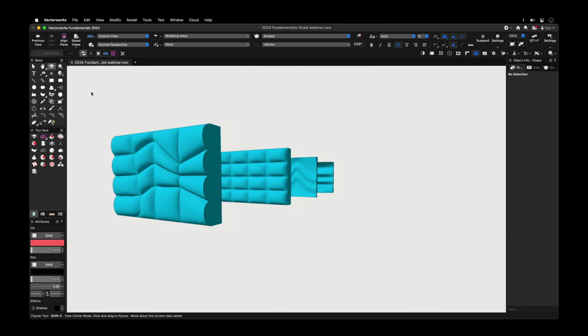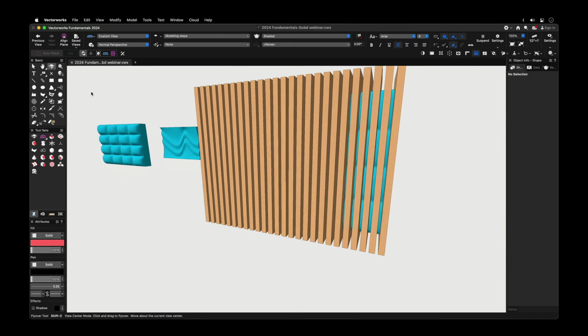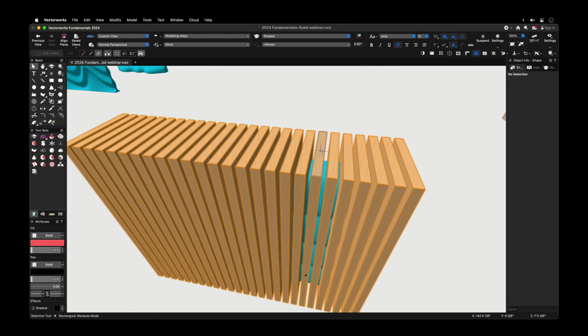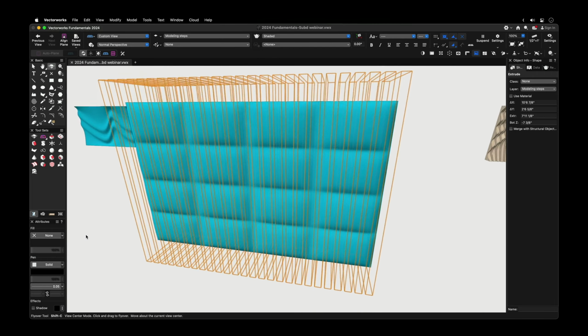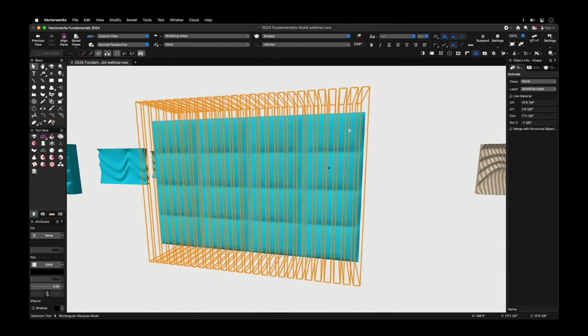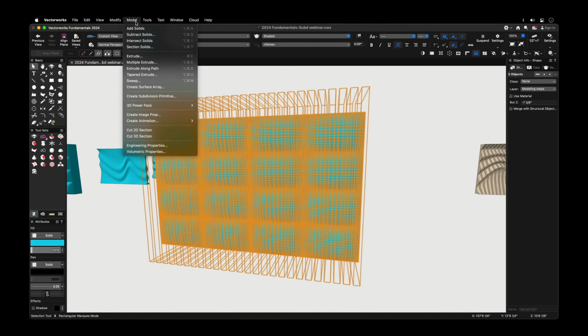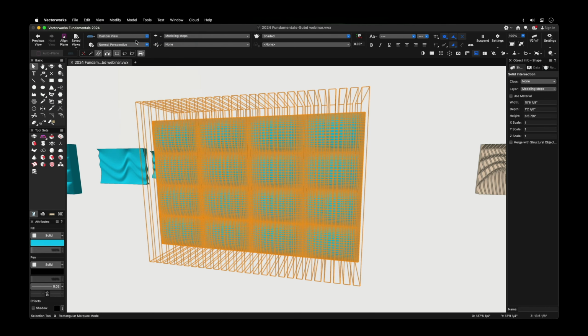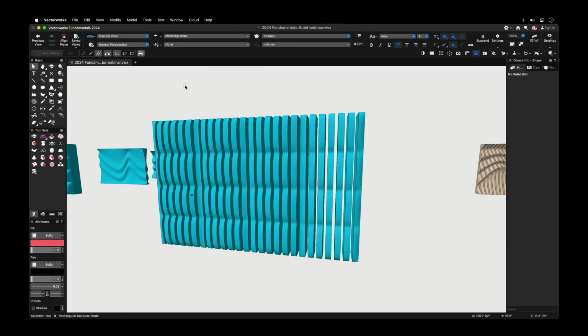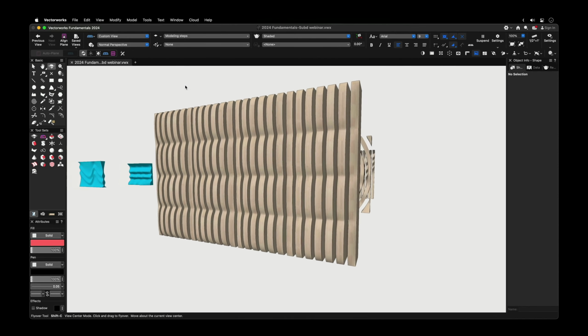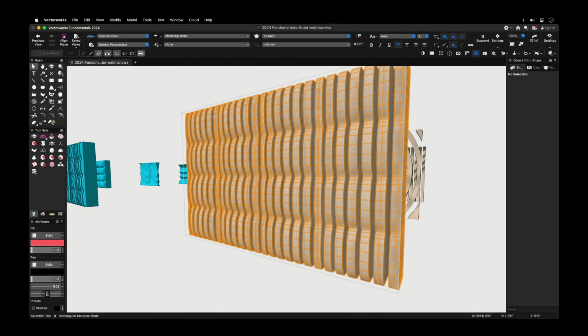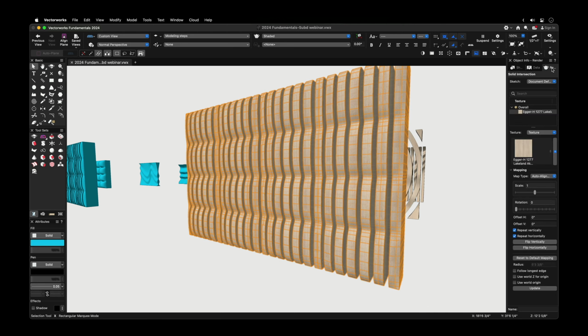Okay, let's move on and I'll show you how we can morph this subdivision object even further. As you see, I have a series of extrudes surrounding the blob. I'll select them both and from the model menu, I'll select the intersect solid operation. Done. The next move will be to add a texture. Just a matter of selecting the object, and from the info palette under the render tab, right here is where we can assign and control the textures and its mapping.